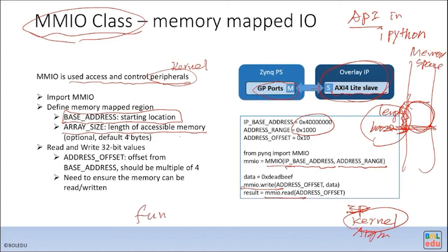You call a function, and the function has arguments A, B, C, for example. When you call the function, you have to provide the arguments, right? The arguments are what I mean by the configuration. How do you transfer A, B, C? You do the MMIO using the AXI Lite interface to program these registers.